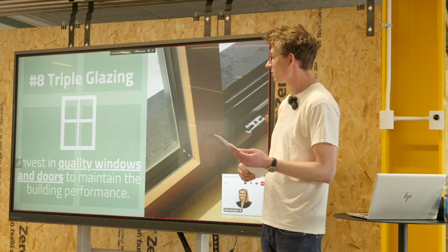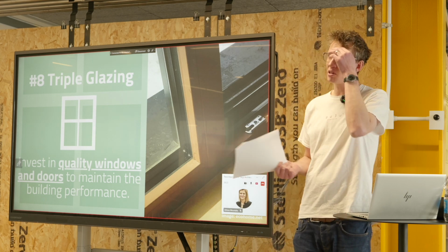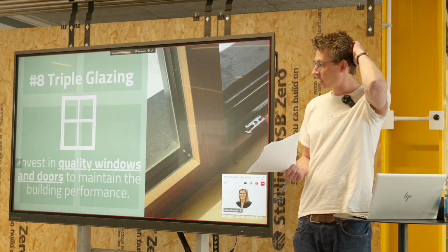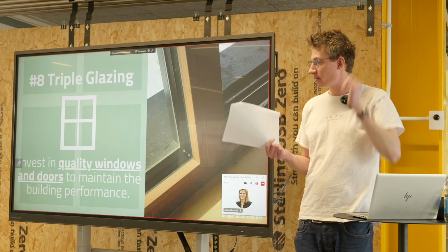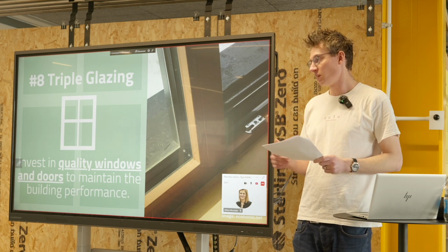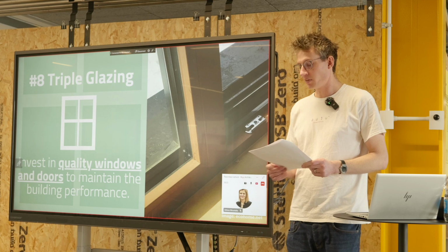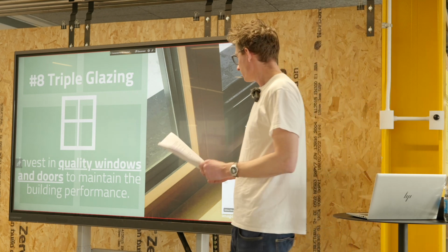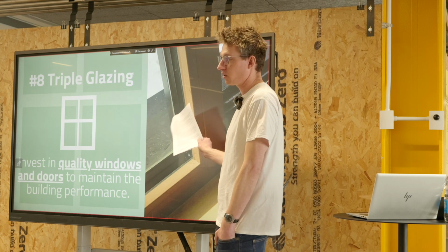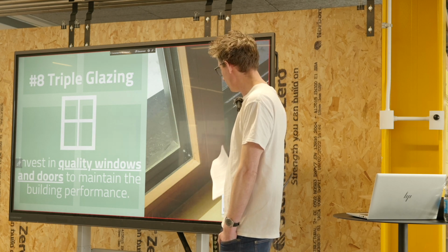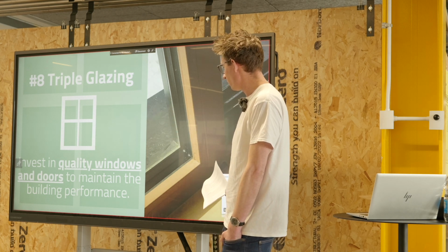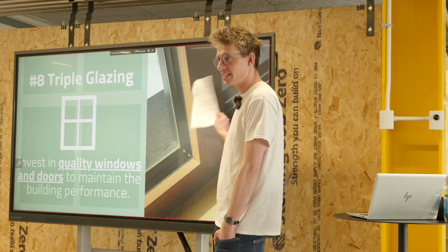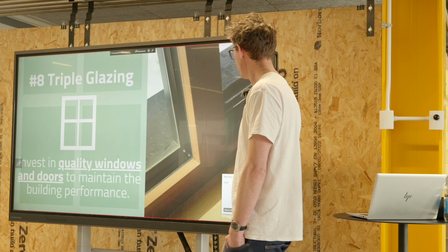So there are certain U values. I don't know if you guys have come across U values for different building components. So depending on where you are around the world, there's recommended U values for glass and also reflectance values. Interestingly, the U value of the glass is quite often not the weakest point. It's actually the U value of the install, or the U value of the frame, or the U value of the spacer. So all of these things have got different U values.